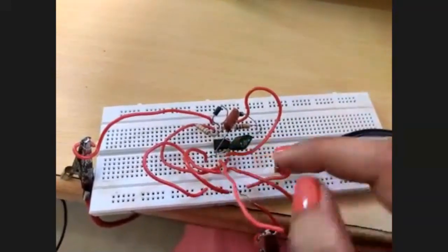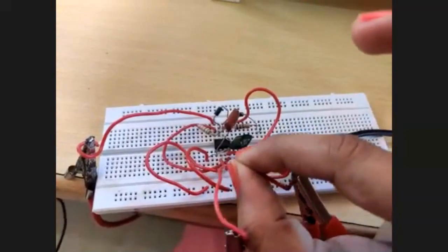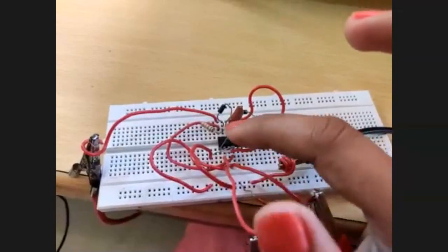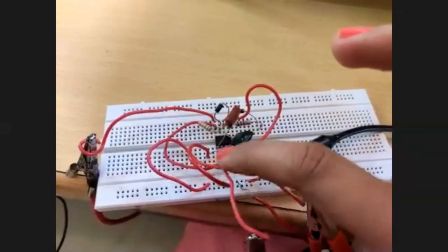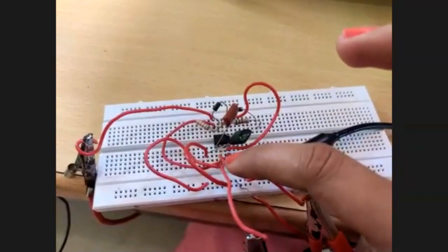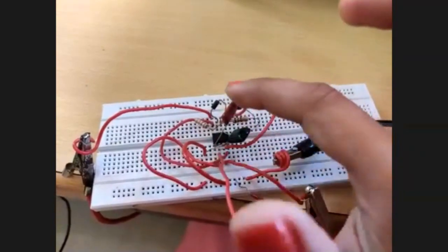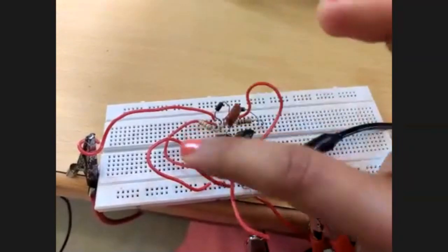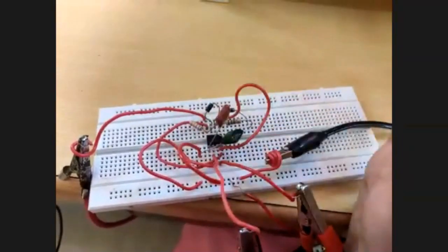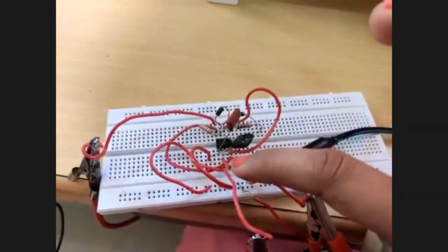This is across pin number 3. Okay, so 1, 2, 3, 4, 5, 6, 7, 8. Anyhow, this 2 is the variation of the capacitor, and this 3 is the output. Or 2 and 6 will be the triggering. Okay, so we are not giving any triggering input for an astable multivibrator. Let's see how we will be getting the output.